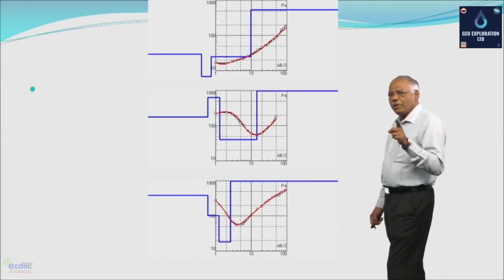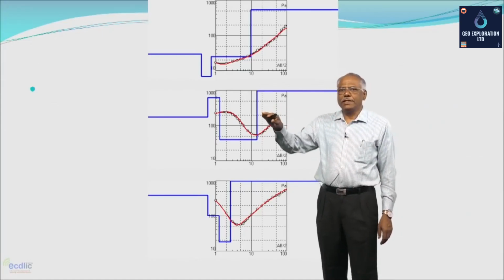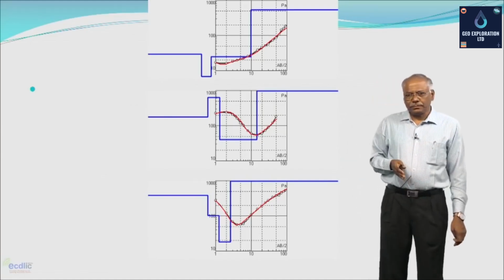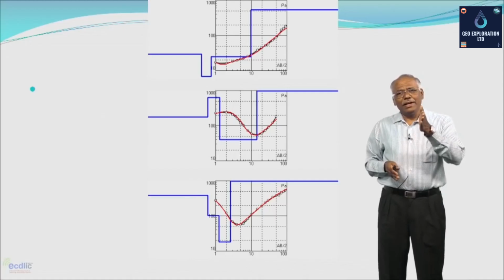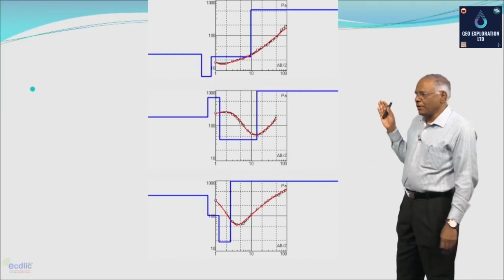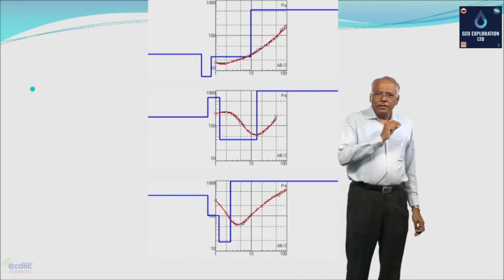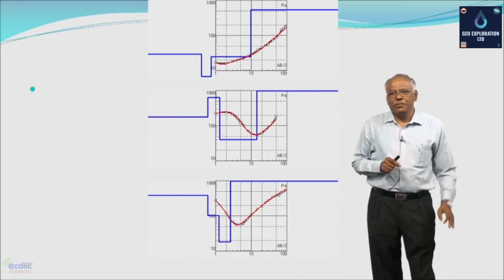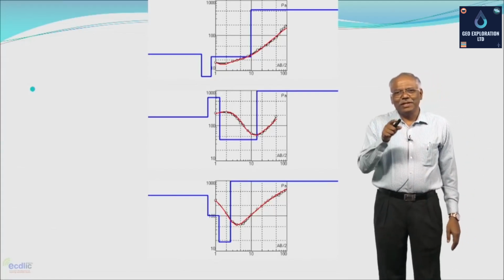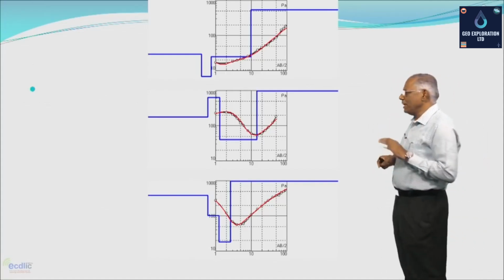In the software, what we get is, on log paper, the horizontal x axis with the depth or electrode spacing, and the apparent resistivity, and as you go deeper, the kind of graph obtained gives you an indication. For example, in the first one here you have the ascending type of curve. Ascending means with depth the electrical resistivity is increasing. That means, theoretically, rho 1 is less than rho 2 is less than rho 3, and this is typically known as an A type of curve.